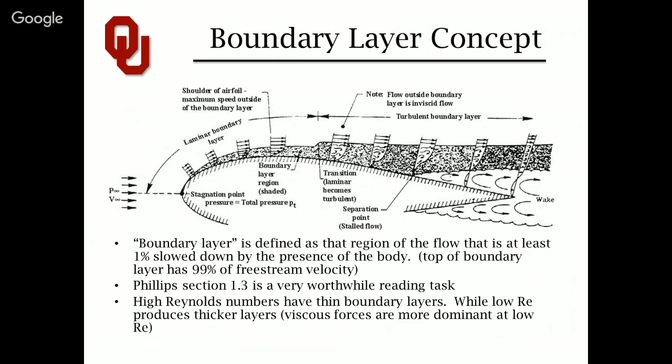But this does depict the transition between laminar, transition into a turbulent boundary layer, as well as separated wake region. You can imagine if we were looking at a circle, a sphere, a cylinder, instead of an airfoil, you'd have a much larger wake region, and then the understanding and ability to model transition would dominate where that flow actually attaches to the sphere, or if it detaches immediately when it hits pi over 2 radians or 90 degrees from the stagnation point on the front. It really changes things quite a lot.